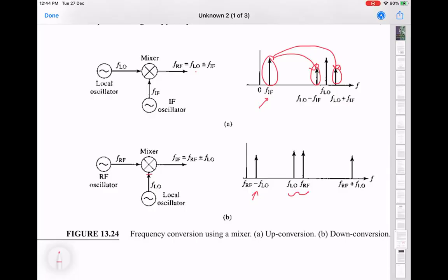That's an example specific for say audio transmission, but this is the same for even video transmission, right? So video signals are not in tens of kilohertz, they are in megahertz. But when they are also transmitted over antenna, they are modulated on a much higher frequency carrier wave. The reason you do that is that higher frequency waves can be propagated easily over long distances. But then you have to bring it back to the usable regime, because you cannot directly hear 100 megahertz. So the information is contained in a very small range of frequencies around 100 megahertz. So you bring it back and then you put it through a regular speaker.